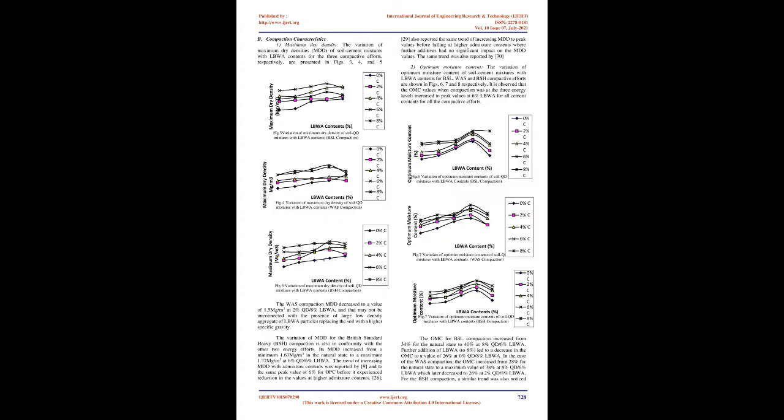The index properties are summarized in Table 1, while its oxide compositions are summarized in Table 2. The soil belongs to the CH group in the Unified Soil Classification System 24, soil group of the AASHTO Soil Classification System 25. The soil is reddish-brown in color, from wet to dry states, with a liquid limit of 43.9%, plastic limit of 29.0% and plasticity index of 21.9%.